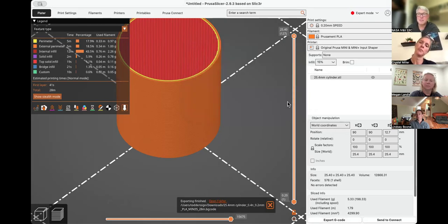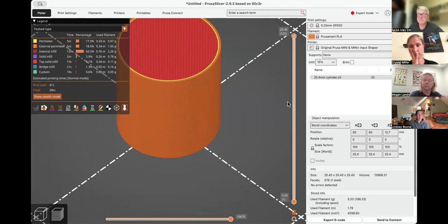So that's the wrap up. We went from a shape, a circle or a square. We used a feature called extrude, and we made it a three-dimensional object. We exported the object out as an STL, a stereolithography file, and that file can be opened by any slicing software.